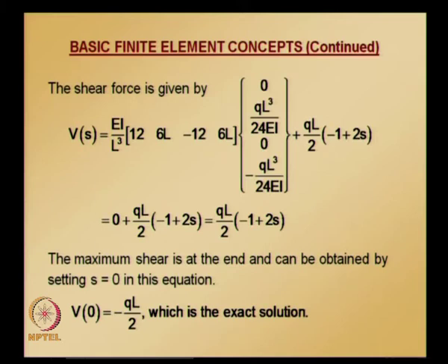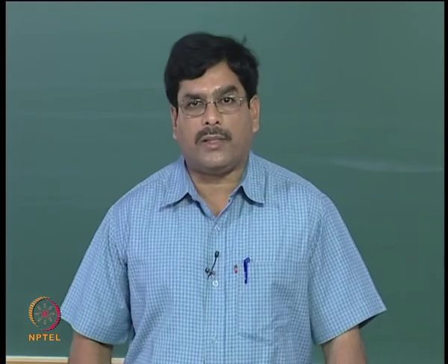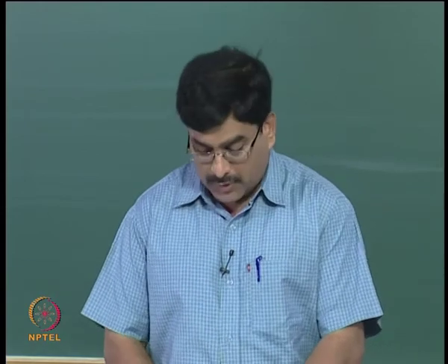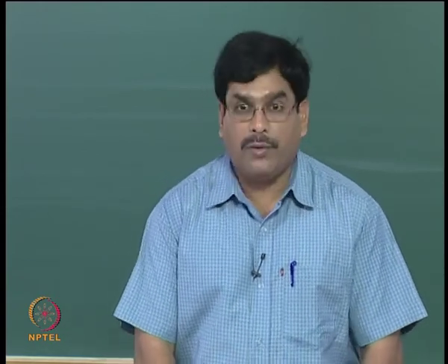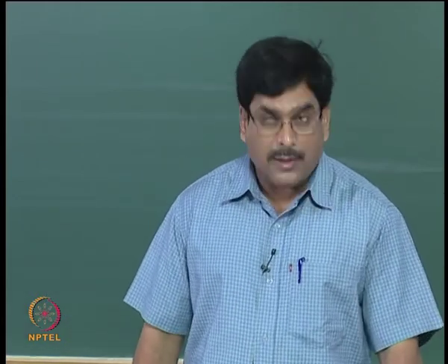We verified this by taking a simply supported beam subjected to uniformly distributed load, and we checked that it matches the exact solution. When we solved the same problem with 2 finite elements without superposition, there is some inaccuracy, and one way of handling it is to increase the number of elements, but that is not a smart way of doing things. So, we will be adopting the superposition method whenever we have distributed load in any span of a beam.